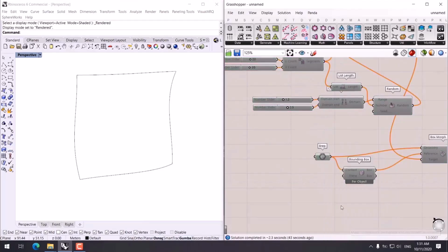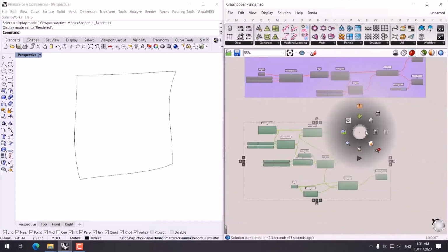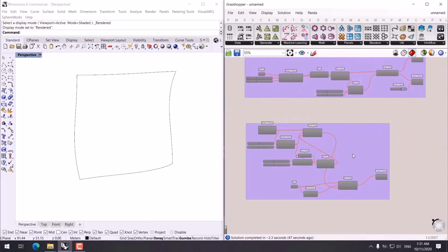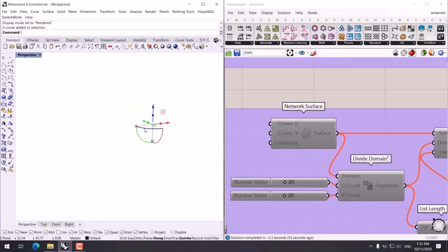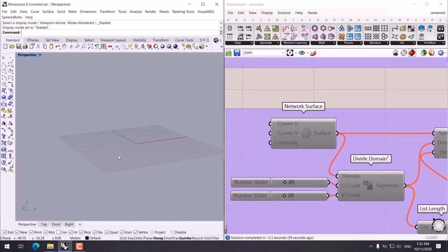Select these, disabled, but I internalize the brep and make a group out of these. Internalize data. So after internalizing them, we will have no problem if we had the items deleted in some cases, since we can use them in Grasshopper.